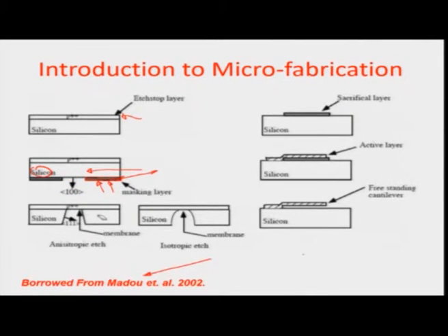You can carry out isotropic and anisotropic etching. This is an example where anisotropic etching is carried out, and this etching happens because of the redox nature of the chemistry involved, and ultimately it emerges as an array of planes corresponding to the 111 direction. Those are the slowest electron releasing planes, because of which you can have this kind of a shape.